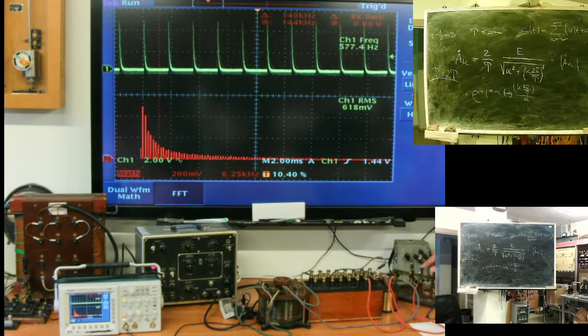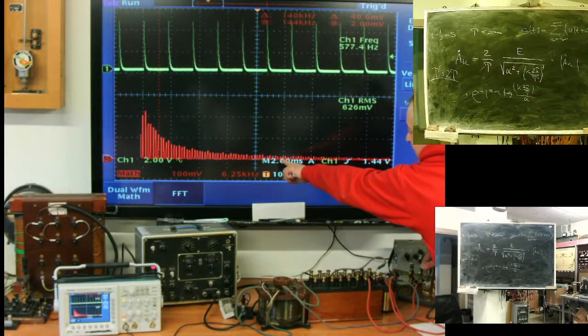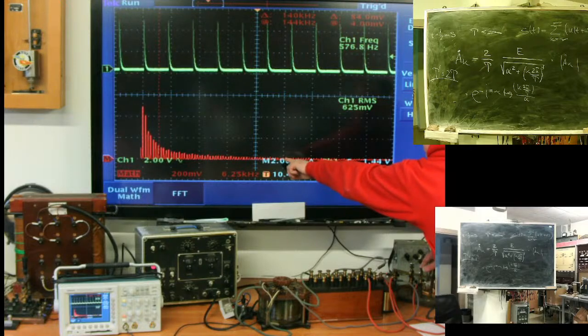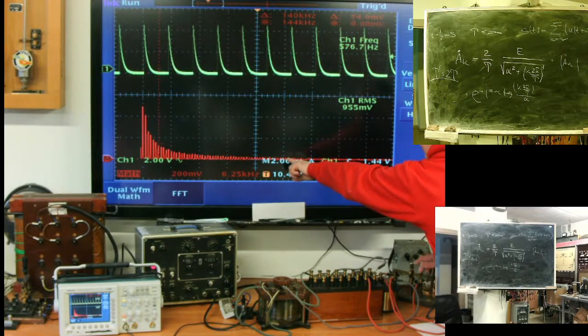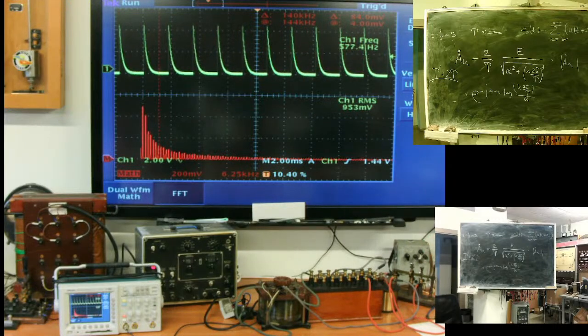Frequency area needed for my signal changes 4 times. You see? Where's the end, where's the tail of the signal? Nothing here, signal here. So the faster the changes, the wider will be the frequency band or frequency area of the signal.